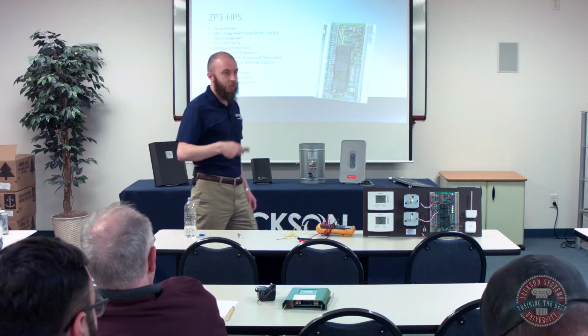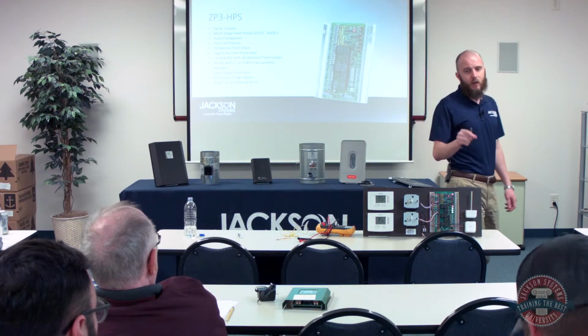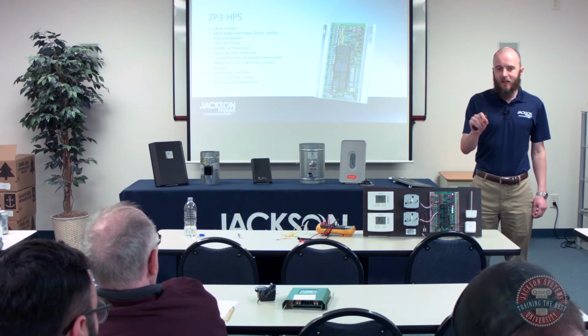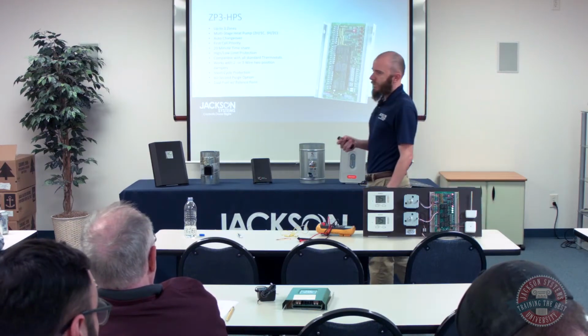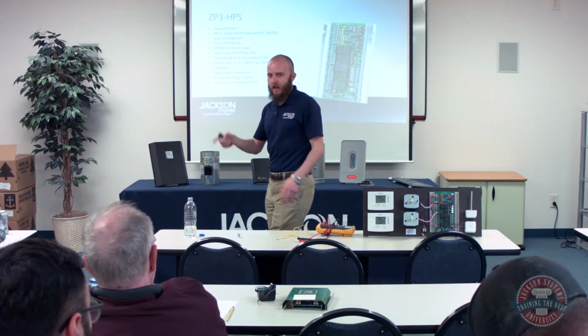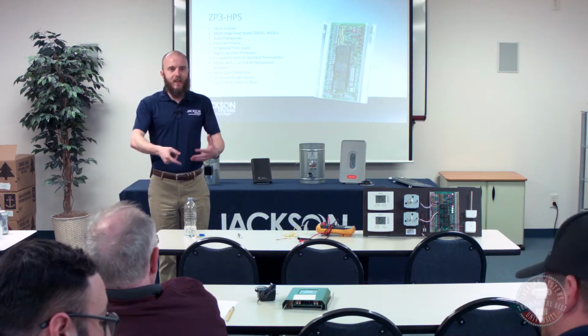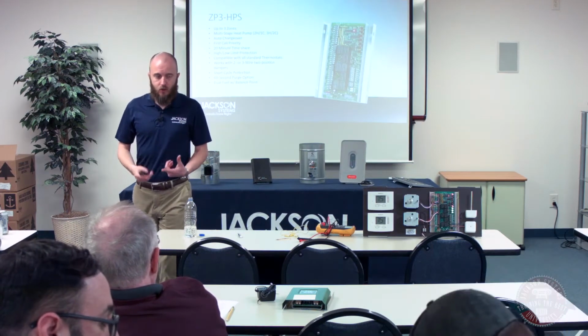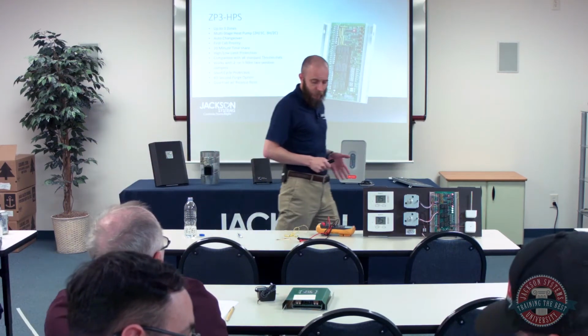working on a zone system, when you're installing it, or when you're doing troubleshooting on a zone system, it's important to understand what that zone panel does and what its sequence of operation is. The sequence of operation is going to help you understand as you go through and do troubleshooting. When you do a step, is the system behaving like it should? So you go through and you systematically do troubleshooting until you find out what doesn't match up, right?